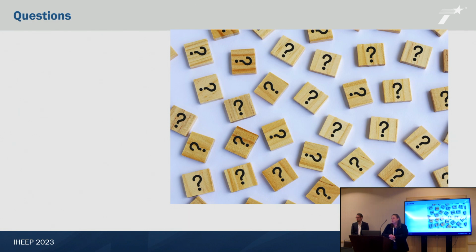Just to follow along with that, we've typically taken the survey and we'll build out using the as-built existing bridge model, and then use the survey to essentially calibrate that model so it fits in space properly, so that we have the existing model with our new models. But we don't rely on the survey for everything. We use some key points out of survey just to geographically locate it so that we know elevation wise and all of that to place it.